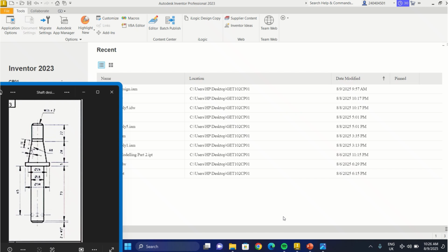In our previous class, we looked at how to create shafts, bolts, and the like on the part drawing. But the challenge we have is that parts like bolts and shafts that should not be sectioned are sectioned in the assembly. And sometimes we have to go back to check that part of the section to be removed. But we could actually avoid that by creating our shaft and our bolt directly on the assembly.